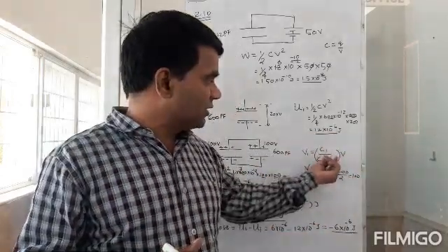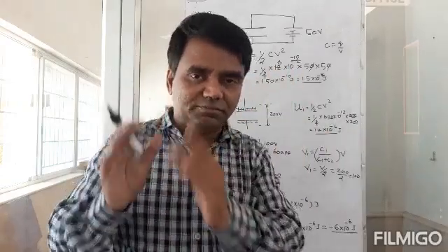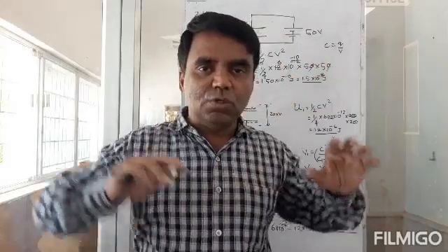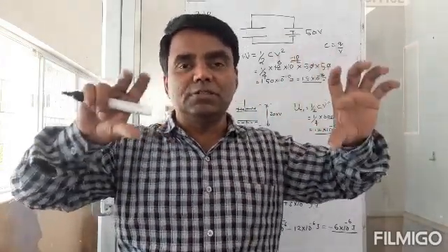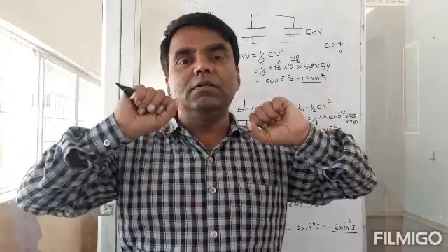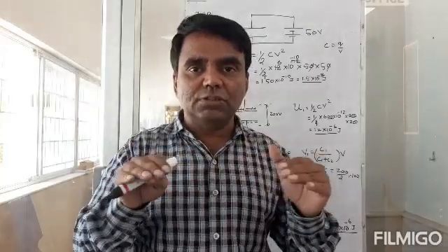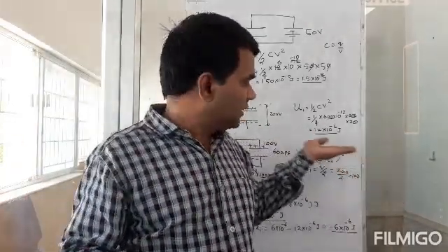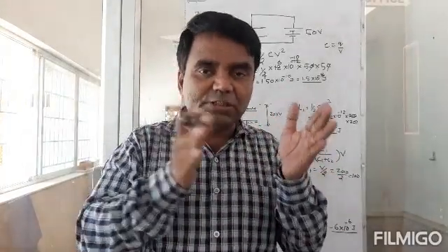So you get this voltage thing, what voltage they will settle at. The initial voltage will be halved only if you are going to connect the same amount of capacitance to this capacitor. Okay. If the connected capacitance is different, then the voltage would not be half of the initial voltage. For example, it's 100, it came down to 50, but that is only because C1 and C2 are the same.